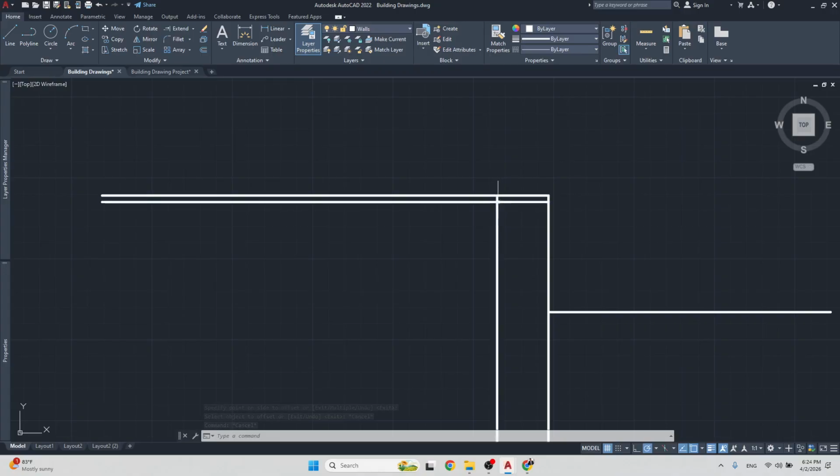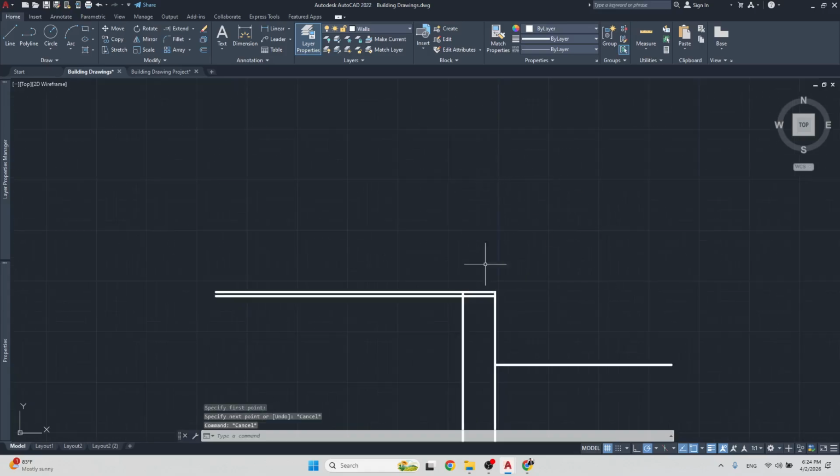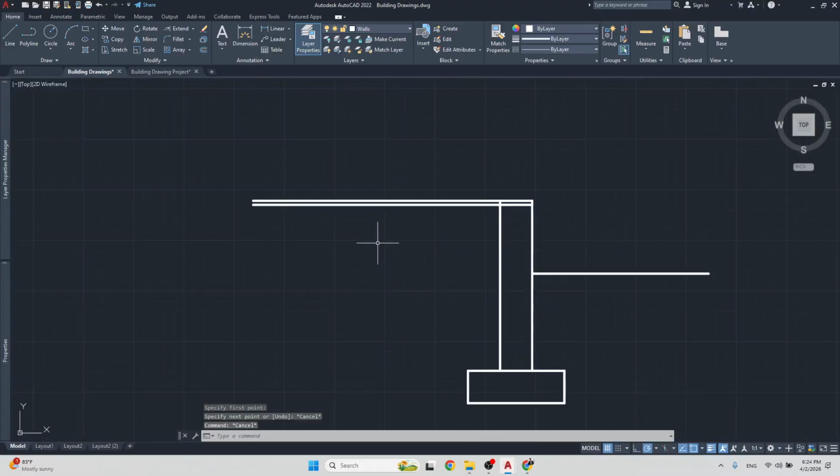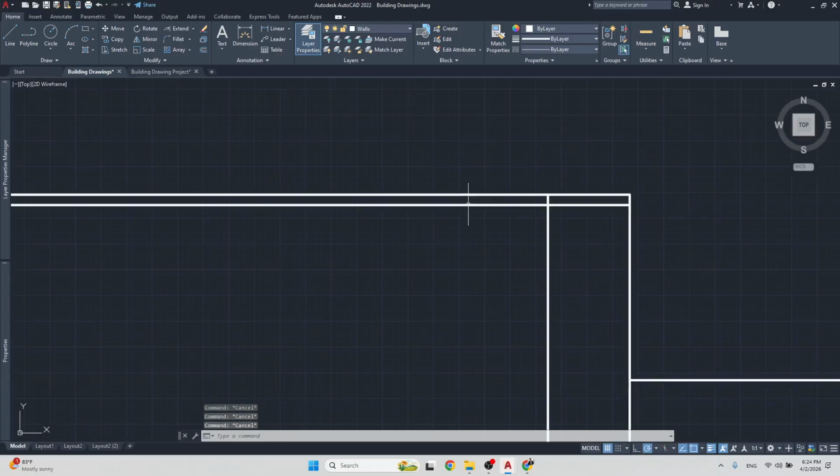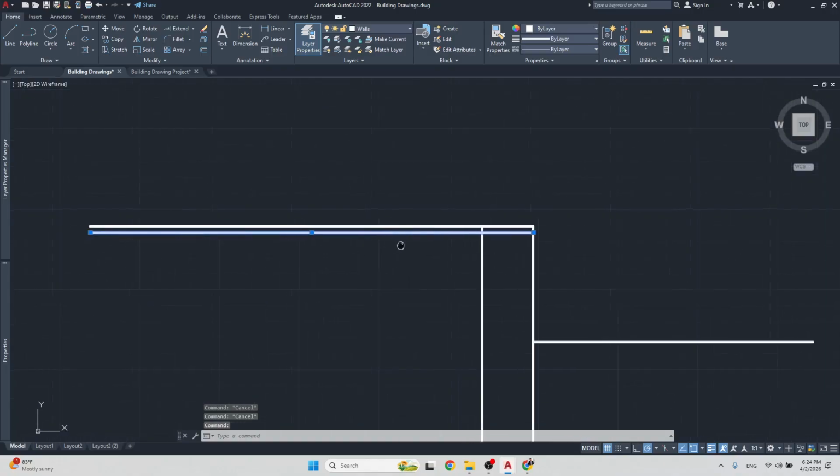we do not build walls on top of the finished floor. So we don't cast the floor, the concrete floor slab, and then plaster it and then build the wall on top of it. No, we would have the floor slab right here, and then we would build the wall on top of that floor slab, and then the finished floor, the plastering, will come up to that wall.